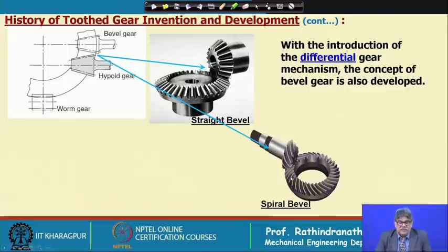Now, next on the bevel gear, if we look into this, this is spiral bevel. The spiral bevel means the same, it might be the same intersecting shafts, same teeth number, but the teeth are spiral, and if we consider the center of curvature, that is somewhere outside this gear teeth, okay. But still the shafts are intersecting, maybe 90 degrees or maybe more than 90 degrees. So, this is spiral bevel, it is close to the helical gear.